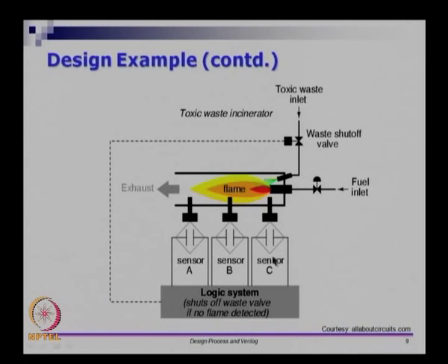What can happen is, these 3 sensors, if they are always working, and if there is a flame, will give 111 as their output, saying that the flame is there. If the flame is not there and the sensors are always working, you will have 000 as the output. However, these sensors themselves may go bad. The sensors are also subject to failure. Maybe this sensor was replaced 5 months ago, and these 2 are new sensors. Eventually a sensor fails, and I may have to replace its battery, or the sensor itself, it could be any of those.